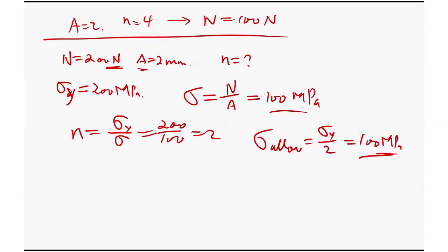And I don't have time to go over that, so your assignment is to try the same problem. Say if I want to put a load of N equals 500 Newton now, okay? I still want a safety factor of 4. You design what the A is supposed to be. Tell me what the A is, right? You can tell me next class. So basically you just try it.